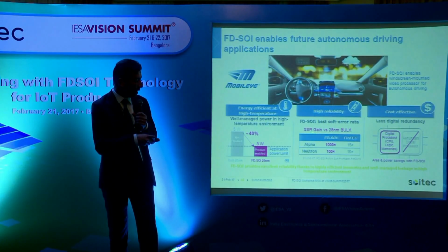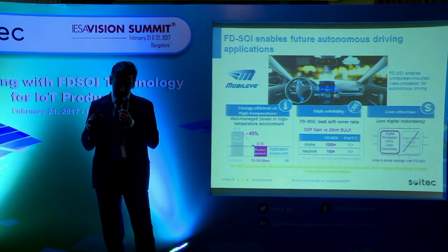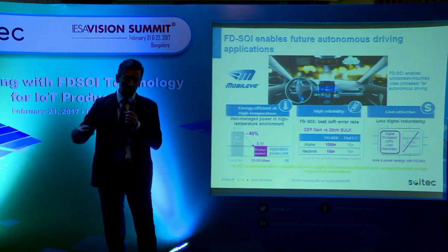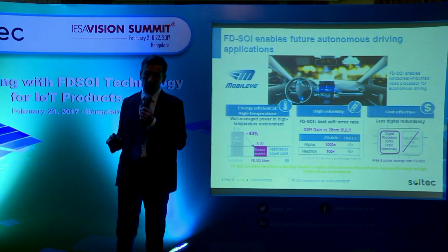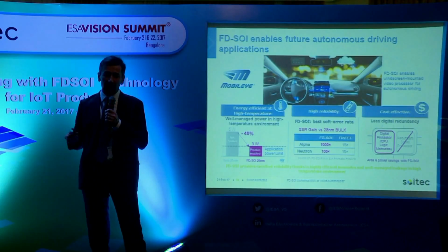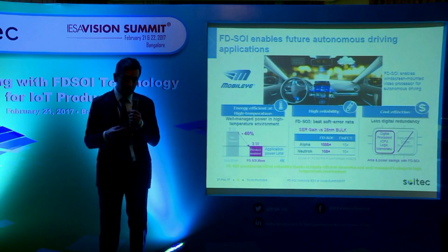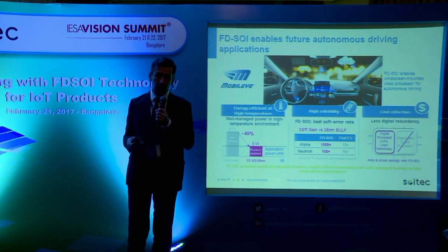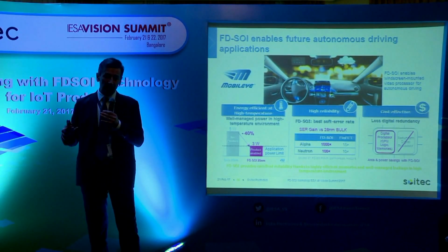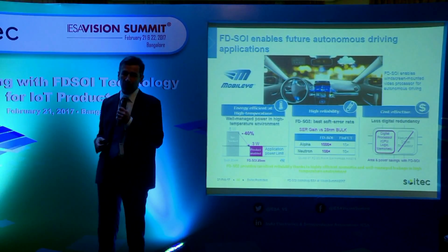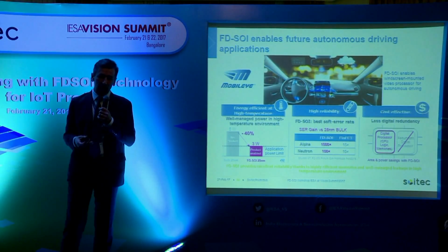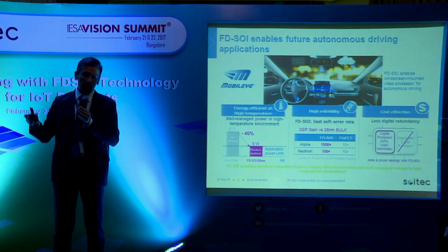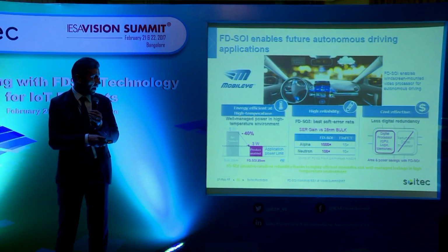With FDSOI having significantly lower soft error, you don't need to worry about having this additional calculation capacity, or this double circuit, just in case of an error. You can design in a simpler mode, and you can see here that you don't need to have redundancy on the chip. So you gain in cost because your chip is smaller and simpler. So this is another key value of FDSOI now being used by car makers, and this is one of the biggest openings for FDSOI beyond IoT, beyond mobility.